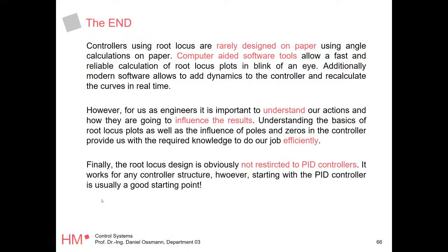Okay, this is basically what I said, and really I think this is what I'm not sure, I added this statement on the weekend one more time. The whole methodology of root locus is really not restricted to PID controllers, but a PID controller is very powerful because it comes along with 2 zeros and an integrator. So it decently brings speed, fastness, and it gives you the possibility to head for steady state accuracy for step